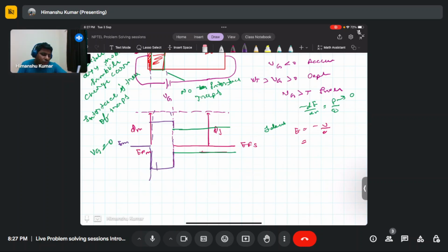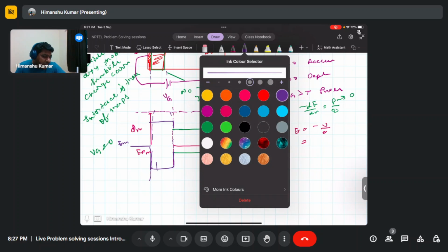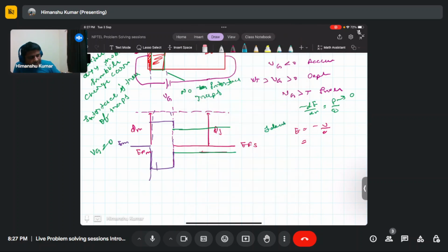Now you apply a negative gate bias voltage. So this will become minus qVG, and because of this the offset will remain the same. And if you draw this band diagram, some potential drop will occur across this region, and this offset also will remain the same. So you can see some bending in the upward direction in this case. Just similarly, you will see here.